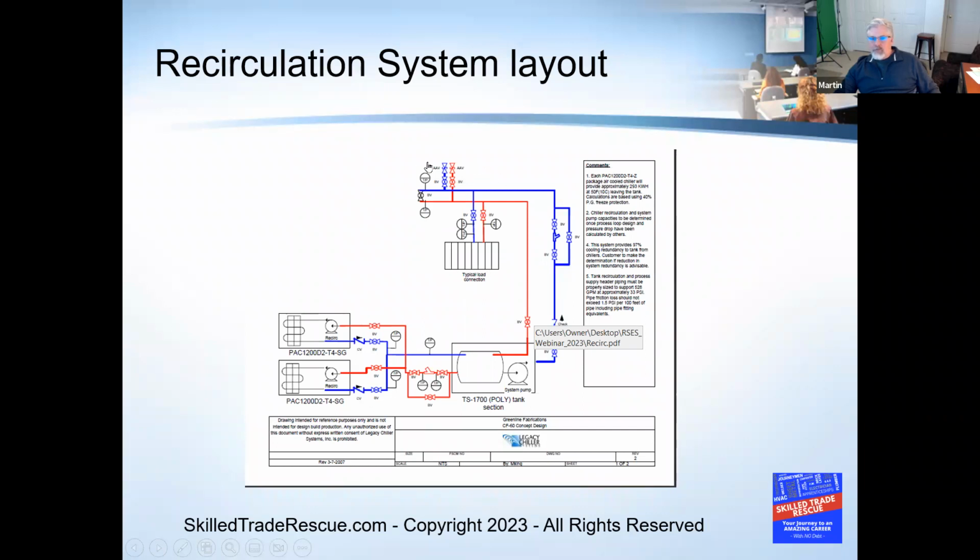Let's say that this whole process requires 50 gallons per minute, the load as well as the bypass. You want to have about 2.5 times that in storage, right? So 50 times 2.5, you want to have about 125 gallons of volume. Now that volume can come from your plumbing, right? But that's the calculation that we used.